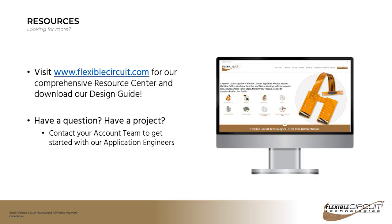We can certainly assemble those components to flex. We do 01005 components all the time, so that's about as small as they get, and we don't have any problems with that. But on very, very large circuits, the larger the circuit is, the more difficult it is going to be for us to define the small features on the flex itself, so it could have some impact on the yields.